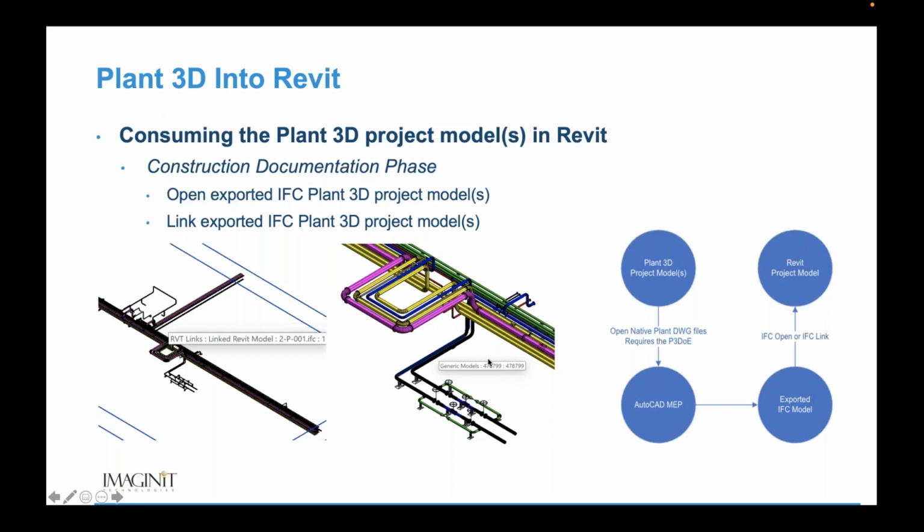The other method of opening the IFC model and actually creating Revit data from the content does give me some additional capability. The objects that I am seeing in the view in the middle of the screen here are not properly converted to the right object types, but you can see that it actually converted it to individual objects inside of the Revit environment that can contain all the same property information that came across from the plant models.